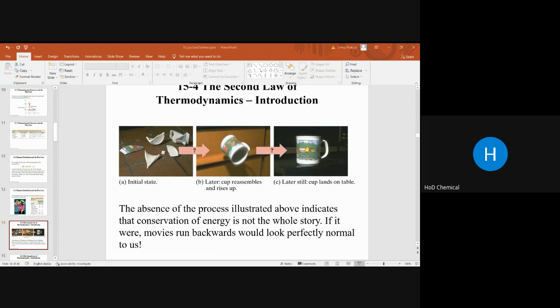Real engines have some frictional loss. From this, we see that 100% efficiency can be achieved only if the cold reservoir is at absolute zero, which is not possible. Real engines have frictional losses, and the best achievement is 60 to 80 percent of the Carnot value of efficiency.